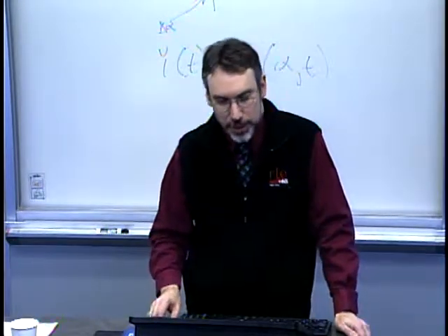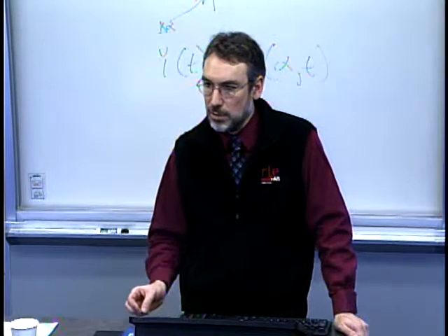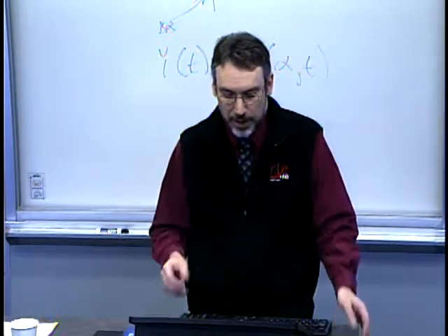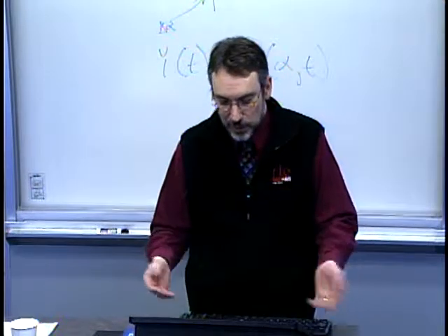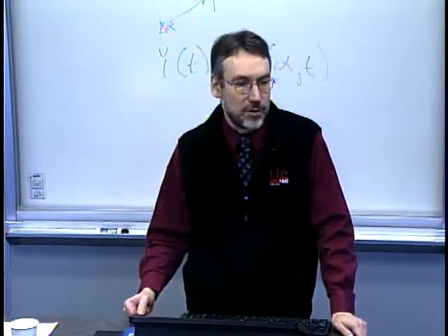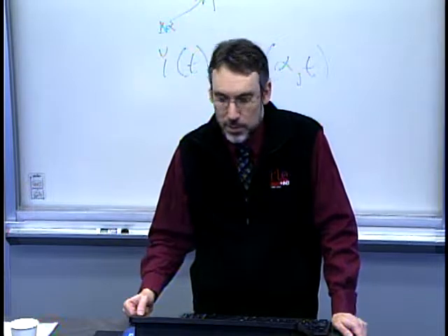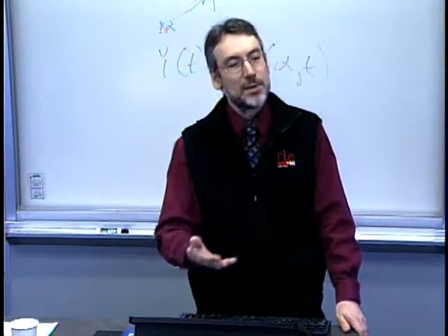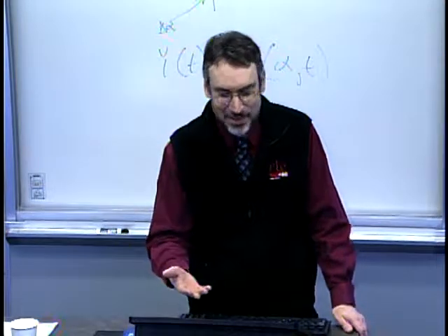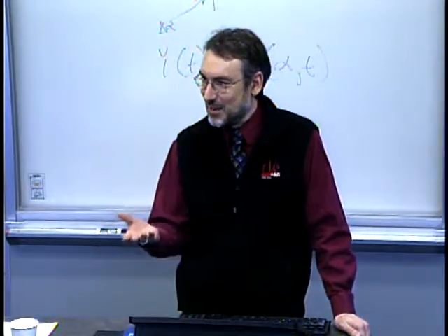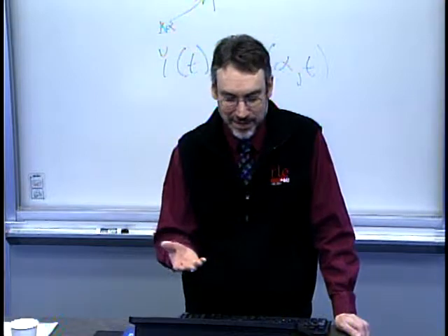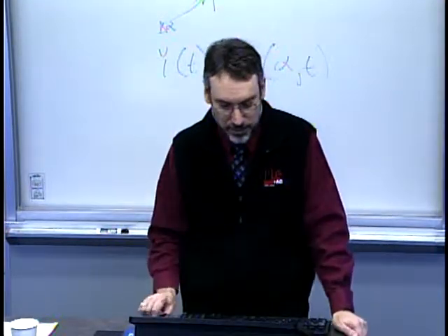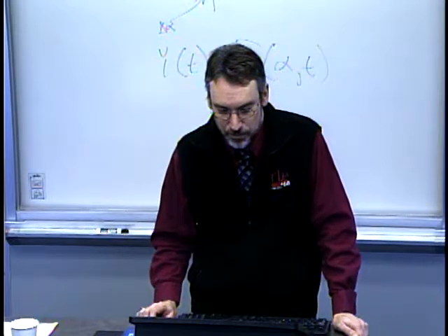And what else is changing here is that the source material is changing. So in some cases we're using aluminum, some cases steel, and also with different thicknesses. So the most obvious observation is, depending on the material type, we certainly get different angles, different degrees of spring back.